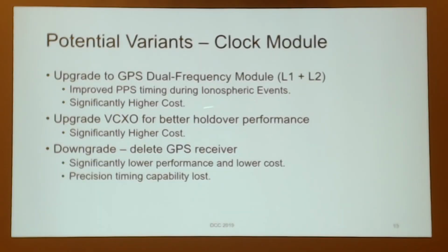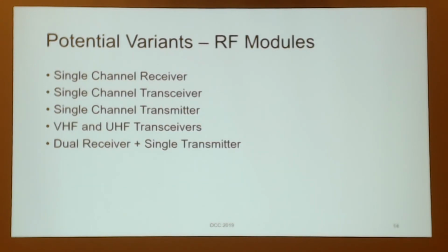We may want to upgrade the VCXO for better holdover performance. That increases the cost because high stability VCXOs cost a lot more money. Or maybe we want to downgrade and delete the GPS receiver. So we have a couple of options there.